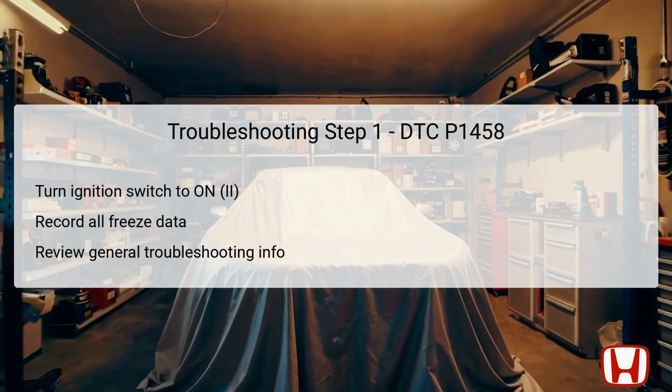Freeze data provides critical insights into the vehicle's performance at the moment the error occurred, while the onboard snapshot can capture various parameters that influence engine performance. Ensuring you have this data documented is crucial for informed diagnostics and repair. Additionally, reviewing the general troubleshooting information ensures you're following protocols that leverage manufacturer guidelines effectively.